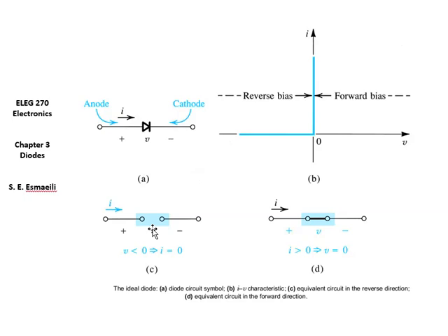Why do I call it an ideal diode? Because realistic diodes actually do have an activation voltage, let's call it a bias voltage. So it's not enough that you just bias it from the positive side. You need to have a certain level of voltage, which for silicon diodes is going to be 0.7 volts, or in germanium it's 0.3 volts. This voltage that you need to turn on the diode is just to overcome that depletion region that we talked about before when we were talking about the semiconductors. But at the moment, let's not worry about that.